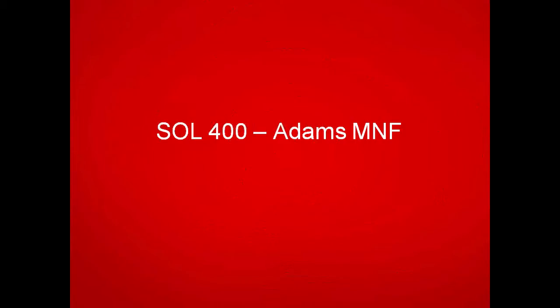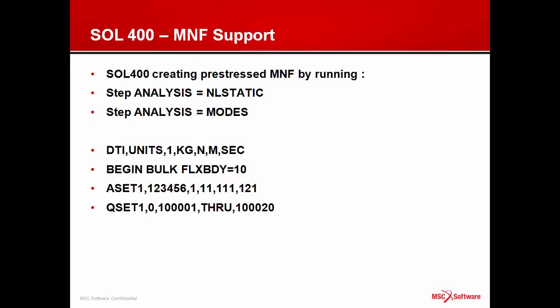Another area of dynamics enhancements has to do with improving the interoperability between MSC Nastran and the Adams product. The mechanism of interoperability is these MNF files, or modal neutral files, but now we can use this in conjunction with SOL 400 so that we can preload the structure, then calculate the eigenmodes of the system based upon that preloaded structure, then obtain the Craig-Bampton modes, then create the modal neutral file, and then migrate that over to Adams.